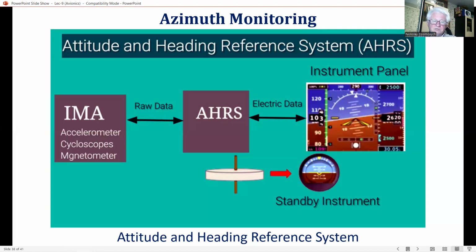The gyros used in AHRS have too high a drift rate for gyro compassing to be effective for initial alignment. Once aligned, the heading accuracy will also degrade with time because of the gyro drift rate, which can range from 5 degrees per hour to 0.1 degree per hour, depending on the AHRS accuracy grade.